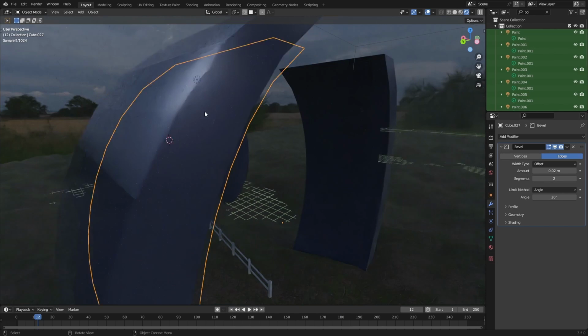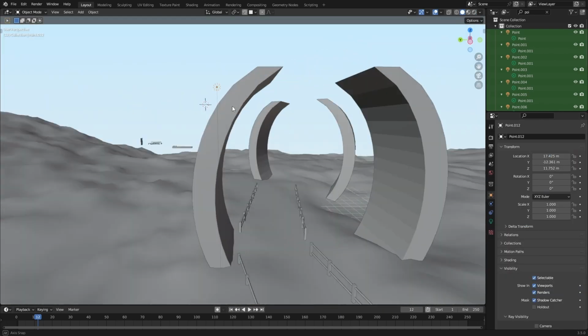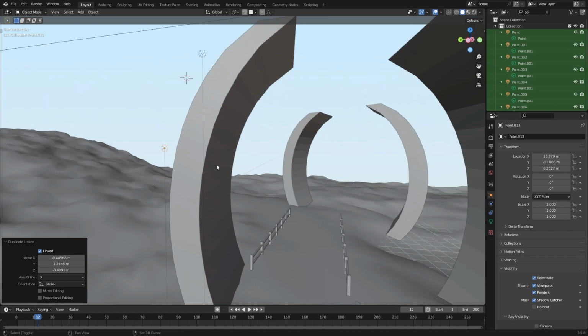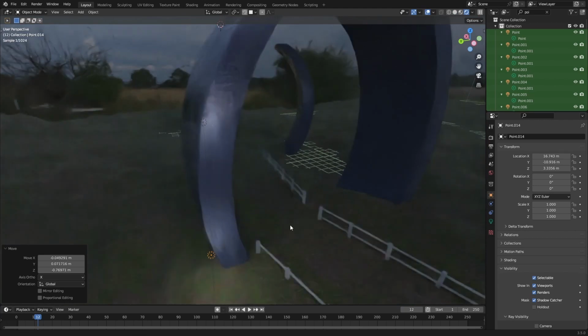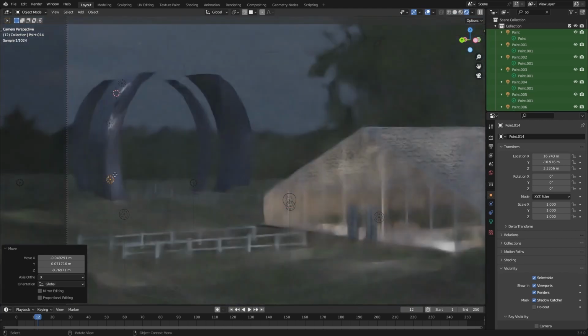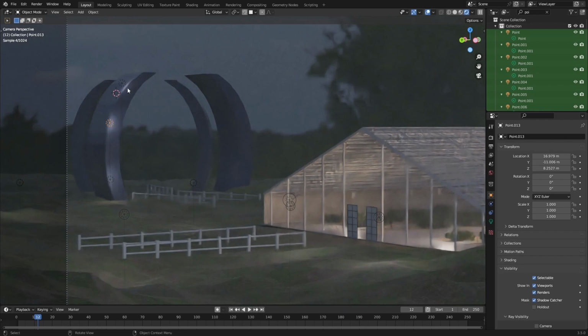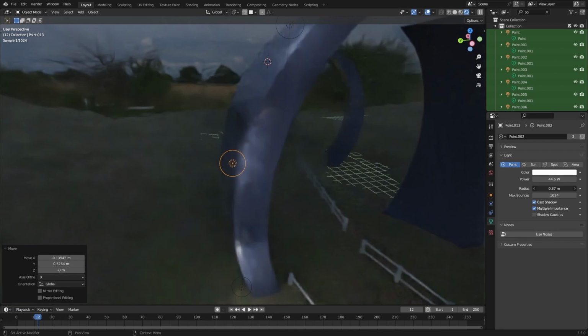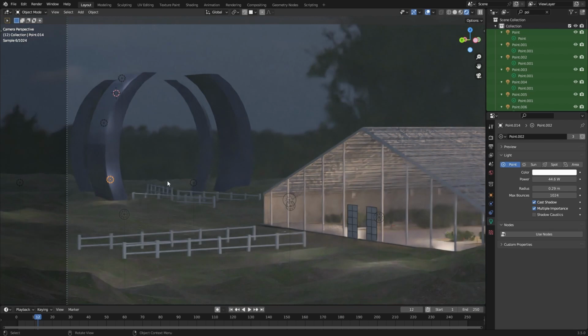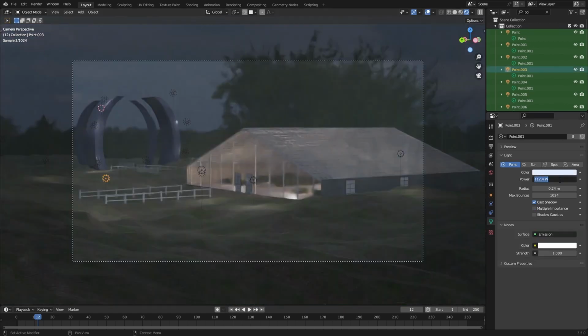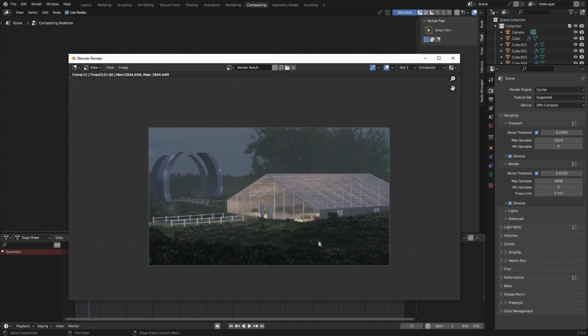So now we get that edge there, and basically just duplicating that, but making sure not to, because right now it looks weird because we have this light here, but then it's dark here, and then it's light here again. Adjust the radius accordingly and adjust the location of the light accordingly. I think that's shaping up pretty well. So I'm going to boost the wattage a little bit, maybe about 250 on the exterior point lights. So now we end up with something that looks like this.